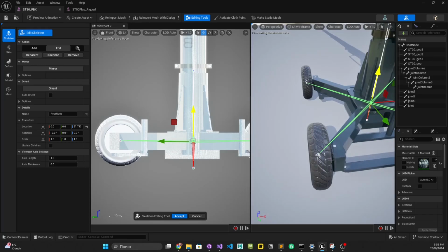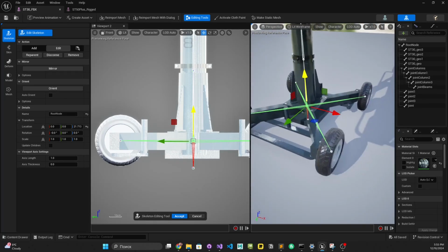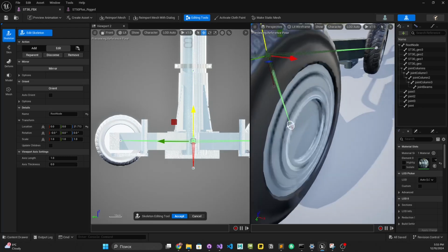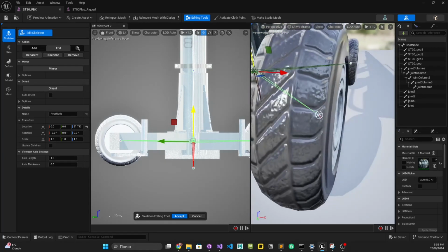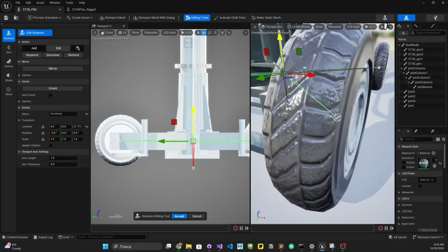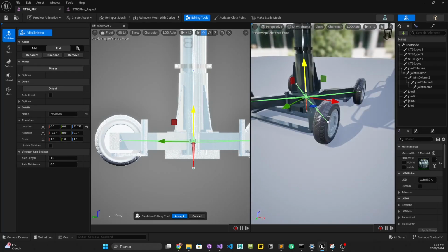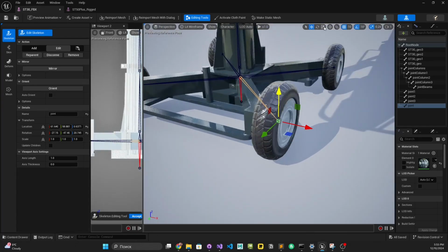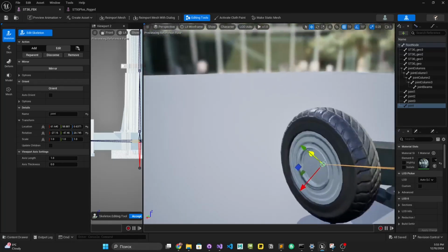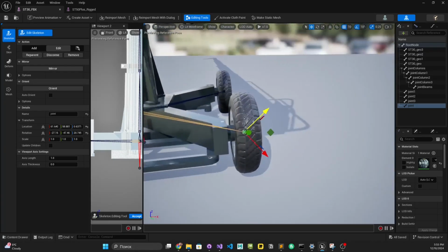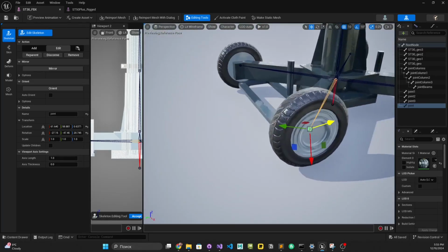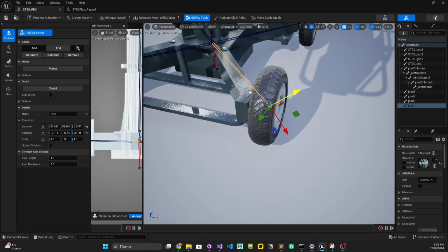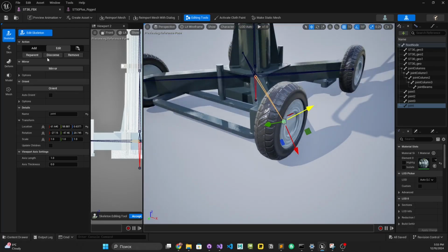And then for the wheels, first of all, we see here that even the wheel joint is created, but it looks like the orientation is not correctly aligned. So in my case, if we select this joint, let's have not a world, but the local axis of the joint. And you see this is absolutely weird alignment. We don't need this. It would be really nice to have the wheel rotated only around one axis. So let's reorient the joint. And we have this option to reorient,